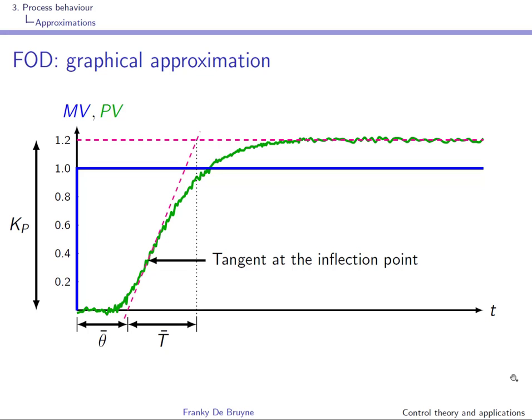So here we have obtained, using experimentation, a unit step response, in open loop, and this graphical approximation method, you'll be able to use it to identify an approximate model for lag time processes, okay, where you have a succession of several first order systems with also possibly a dead time.